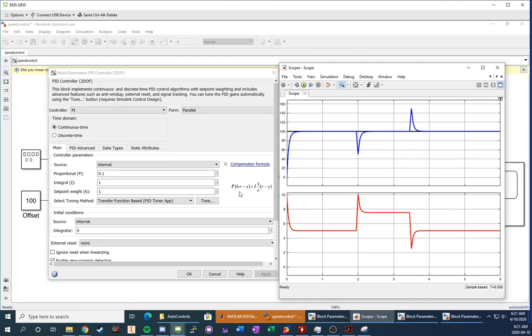Next, go back and actually plug in some of the values that you got for KP and KI from your different methods throughout this lab procedure and verify that they work, and whether it is a good choice for low disturbances in this case, and how it compares to the others. So just include plots of each one of those and make notes, justify your answers, and hopefully you learned a lot from doing this lab.